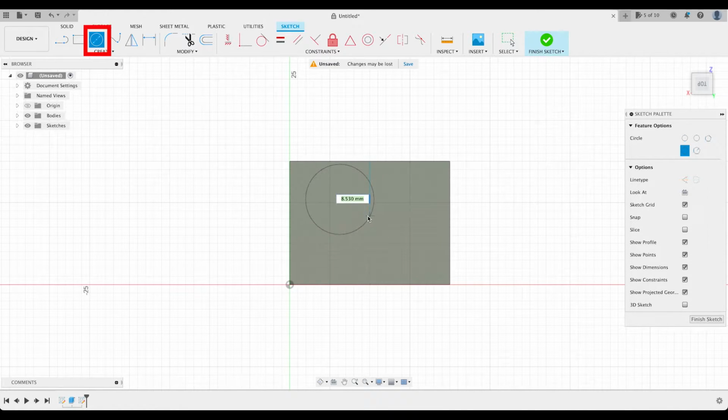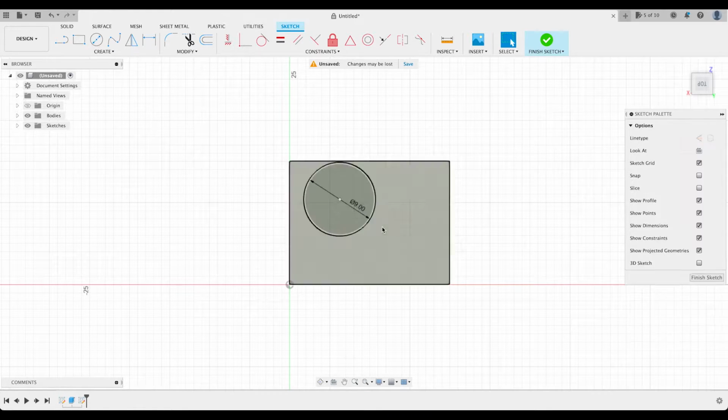I'm just clicking on the face, anywhere, any size, and just like before, the dimension is highlighted in green, and I can change that. So let's make that a 9mm circle diameter. I enter that, but I want to center it, and so we need to remember the dimensions of our face, the initial two-dimensional rectangle when we created it.